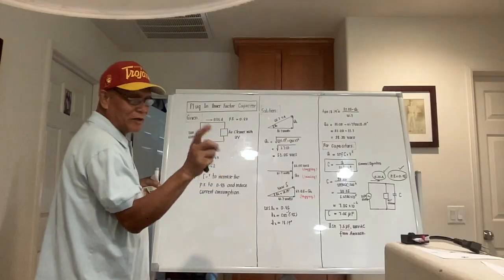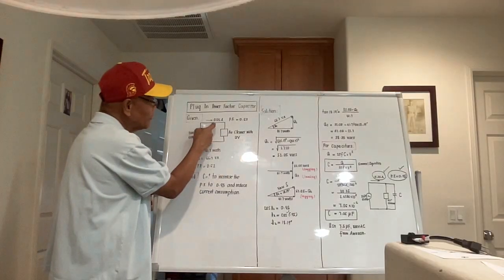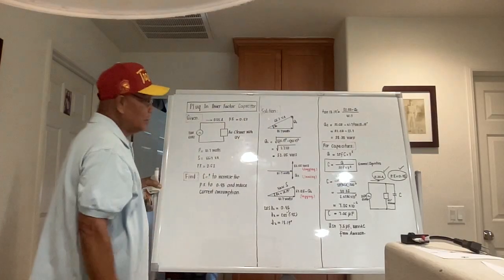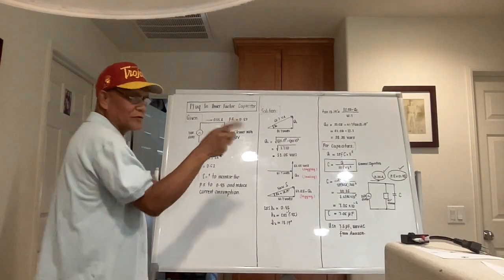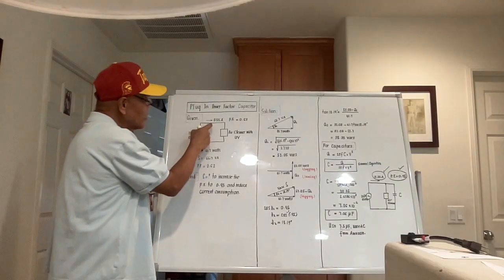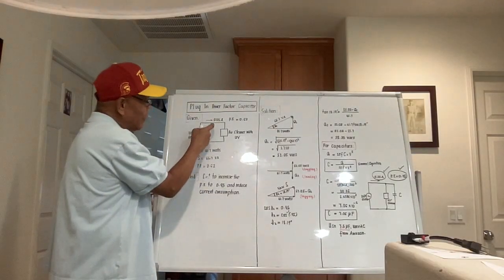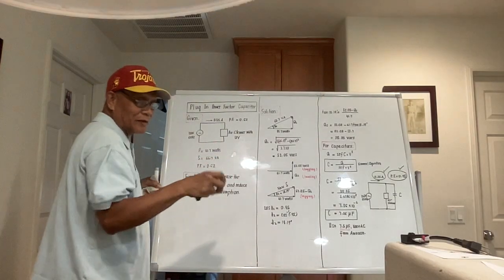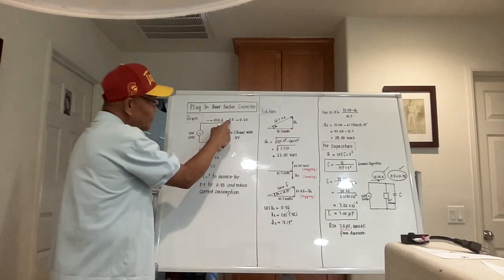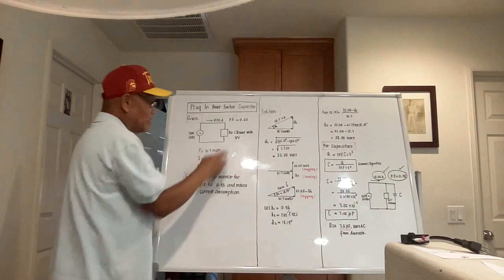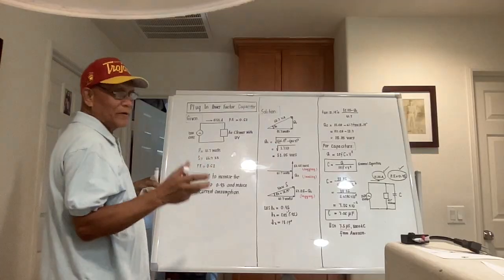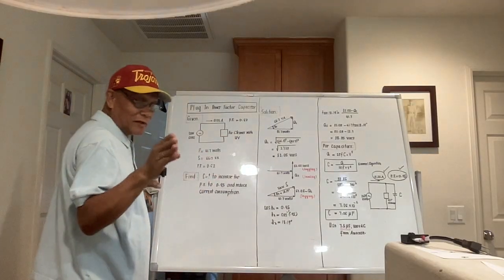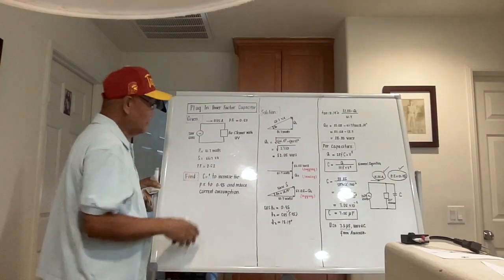I monitored the current consumption of the air cleaner to be 0.55 amperes, and the power factor is 0.62. 0.55 amperes is not so much, but I am not satisfied with the 0.55. If I could lessen this one to 0.1 or 0.2, okay, much more that my electric bill will be lesser. The power factor is 0.62. So the given parameters, if we operate this air cleaner here, that was in my last long video format.